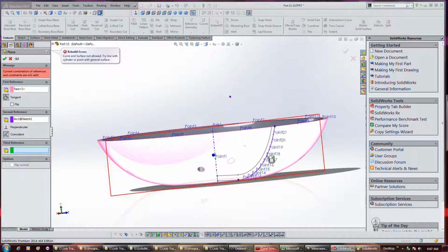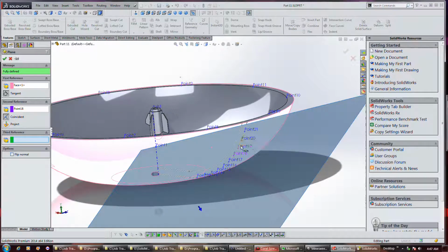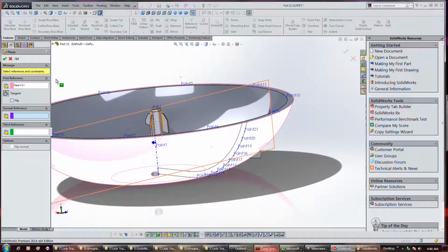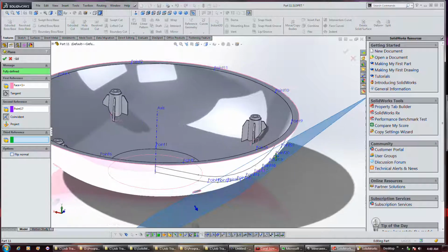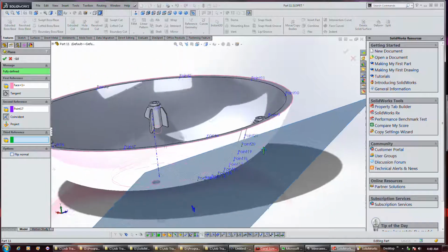But you can't figure it out. So anyway, okay, apparently I just had to select the text of it to make it work. So again, first point's set to tangent, and I'll choose that point, and you can see that that does make a tangent plane to that surface.